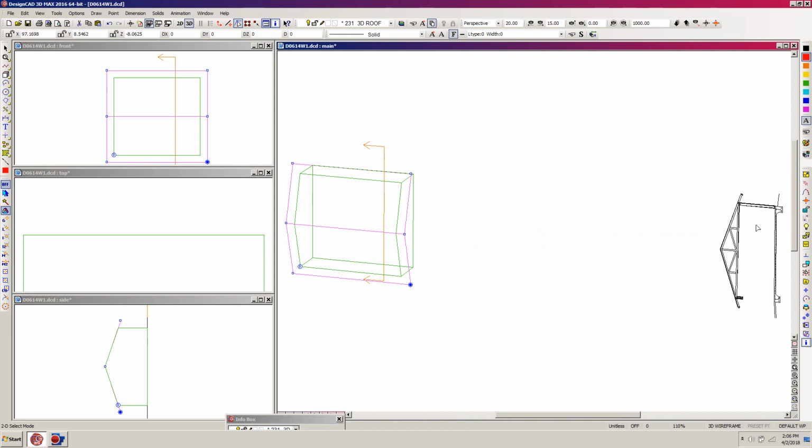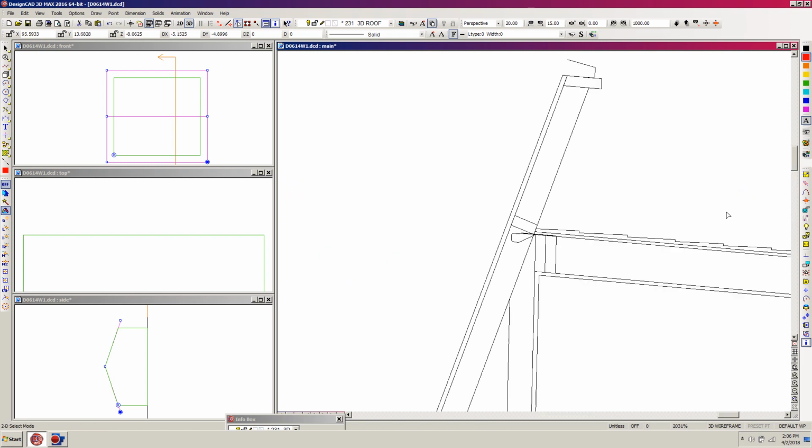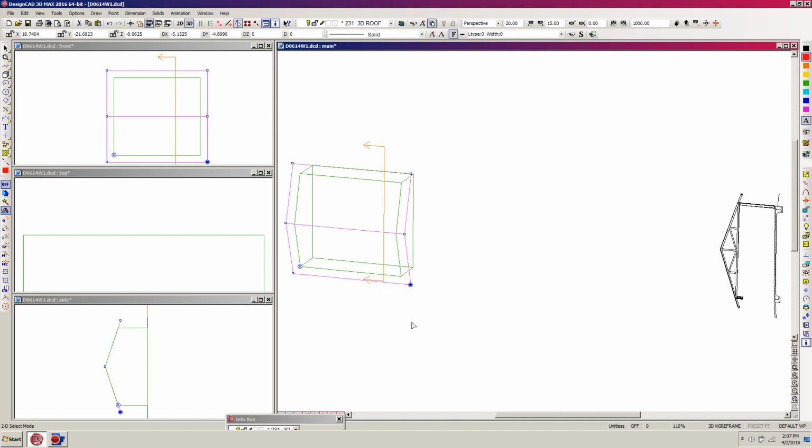And if I could not remember what that 0.3623 is, I could zoom up, hit Z for zoom, and go over here to this red line, which is actually no longer there because it was in the roof line. Doesn't matter. Control W, and I'm just going to hit X now. I could have written it down, I guess. I'm going to right-click on one of the selected points of the roof, and actually you can either right-click or hit the period, either one works, and put the point.